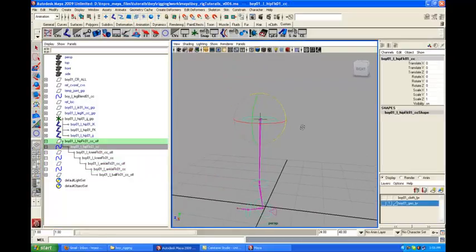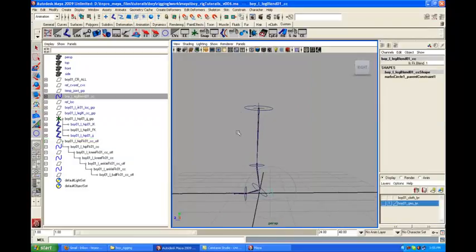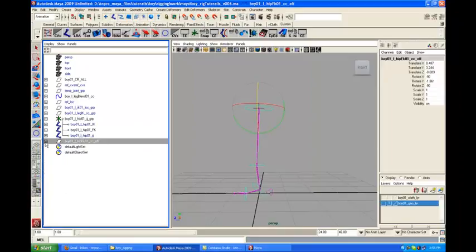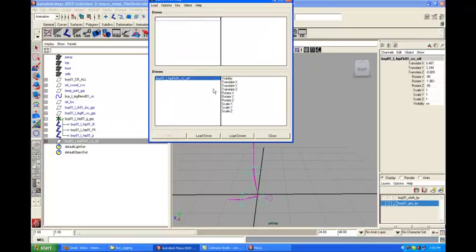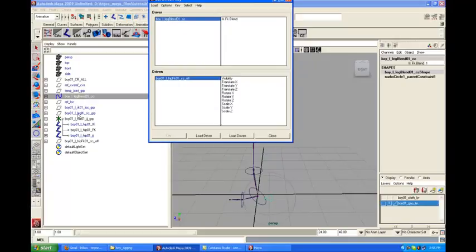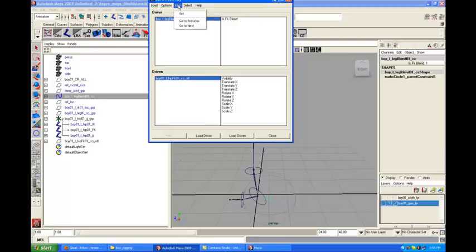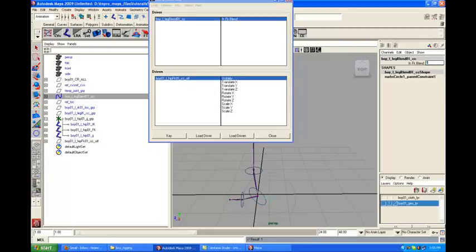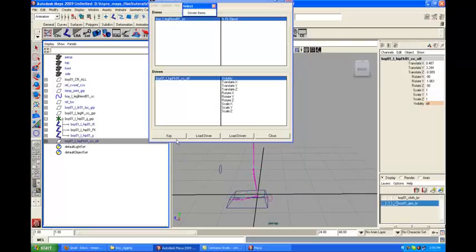So now what happened is, it moved along with the main hip joint and working properly. So let's go to the blend, and what we can do now is we need to hide this control while it's on IK mode. So go to set driven key, load this as a driver and load this as a driven. So it's on 1, so select this and select visibility and key selected and select driven items, okay, and put it on 0 and select driven items and make it 0, okay, key selected.